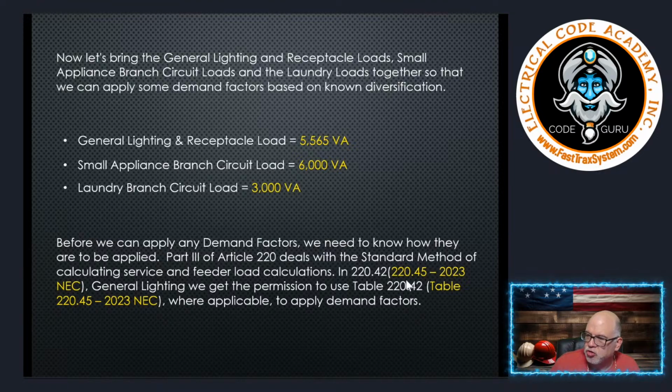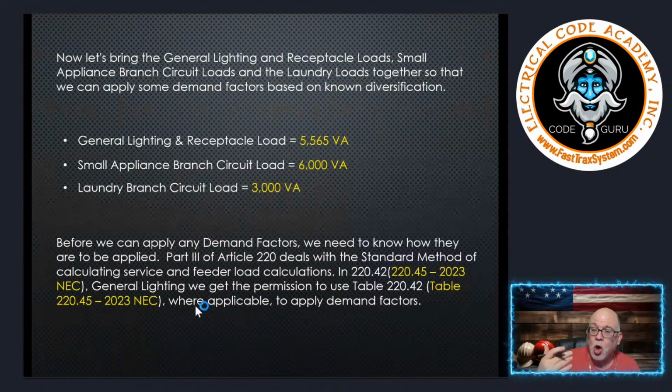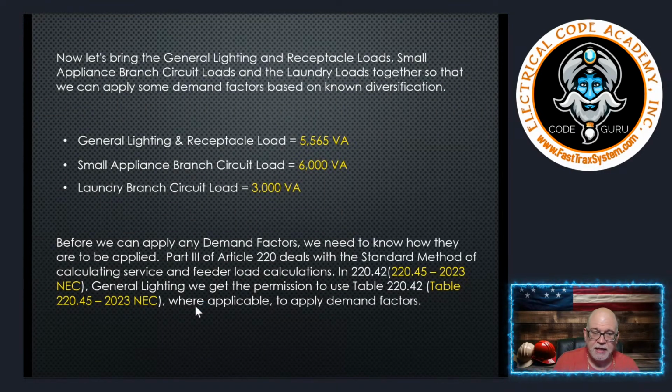So 220.45 gives us the permission to do all this, and we have the general lighting also include those general use receptacles. They're included in this demand.